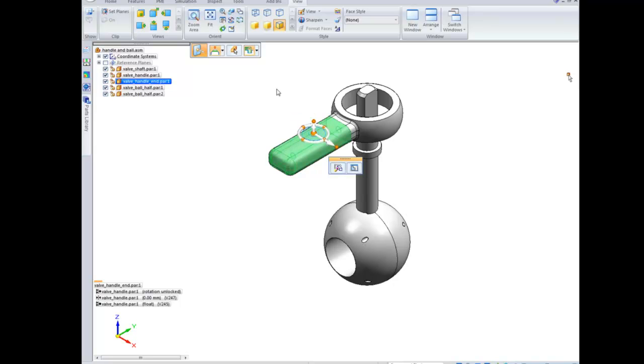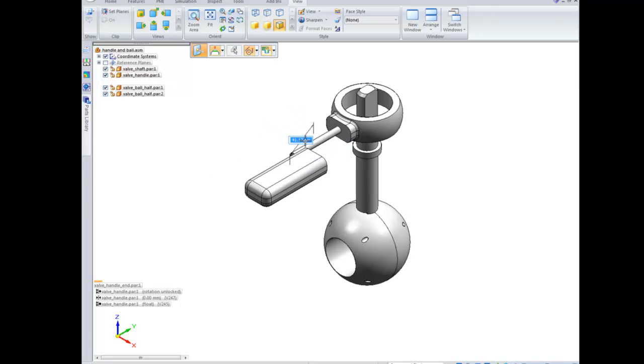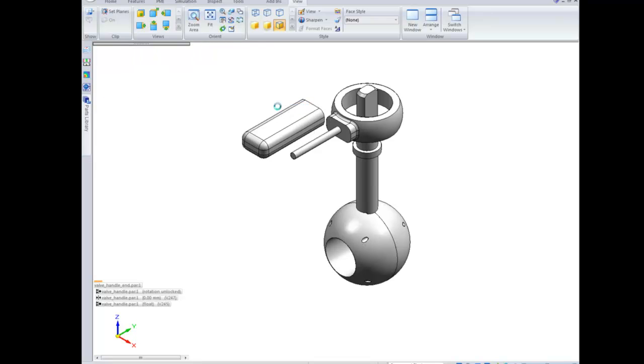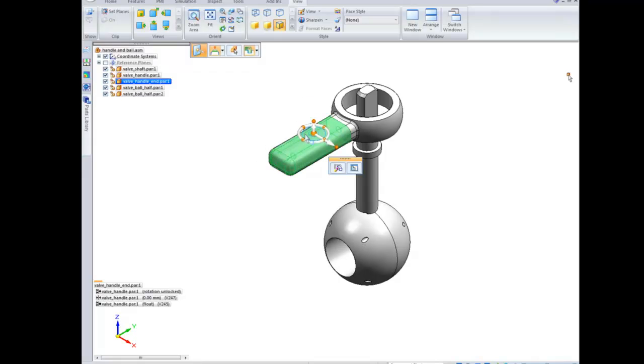Also, if you hold control and click the plane, in an assembly, it'll let you move that part freely around. If you're in a part, you can select all of it, do control and click the plane, and it'll create a part copy for you.